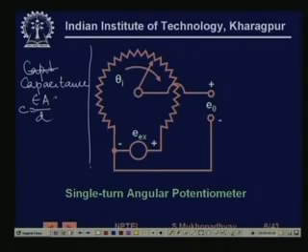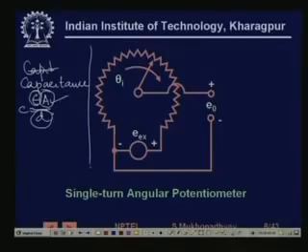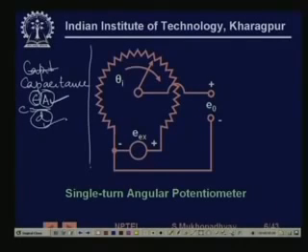So change in capacitance can occur either due to the change in the area, or due to a change in the plate separation, or also due to a change in the dielectric medium, right. So these principles, all three principles actually can be used for making capacitive sensors. In the case of motion sensing, typically change in area, geometrical configurations are used where due to the motion either the area changes or the displacement changes.